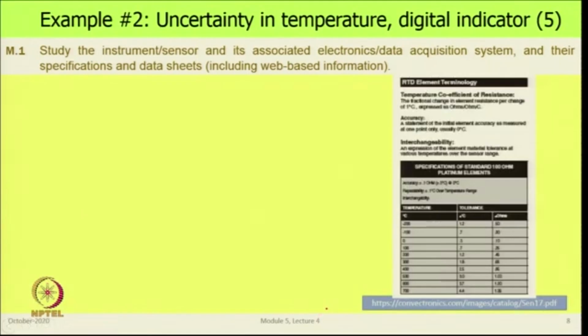So, here is yet another one, but this time it is for RTD, which is the resistance temperature detector. This is also very widely used in industry for temperature measurement, although it has to be used with a stainless steel shield, whereas the thermocouples we can use without a shield also, and those could be much smaller than RTDs.